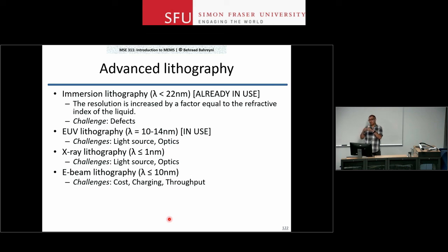Well, those masks, the mask plate is made by having a glass plate, covering it with chrome. Actually, it is chrome oxide or sometimes ferrous oxides, but anyway, some material. Then you use E-beam lithography to define which areas of this chrome you want to keep by covering it with usually a negative photoresist, pattern transfer using E-beam lithography, and then removing the photoresist and then subsequently chrome that you don't need. The challenge with E-beam lithography is that it's a sequential process, right? So you pattern, it's a beam that goes right and let's say draws patterns on your wafer.